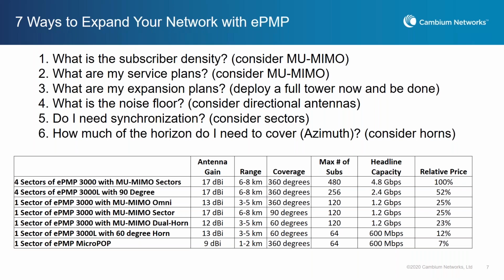Synchronization is really a key attribute of Cambium's point-to-multipoint systems. But if you're going for a MicroPOP application, just lighting up a handful of homes, maybe you don't need it and you can get something very low cost to get started and get that revenue flowing and get those customers served in the real short term. And then the last question might be, if I'm on the side of a mountain trying to hit a particular community, or I'm on one side of town at a water tower and I can hit that community with a 60-degree or 90-degree coverage, maybe I can get away with just a single sector.